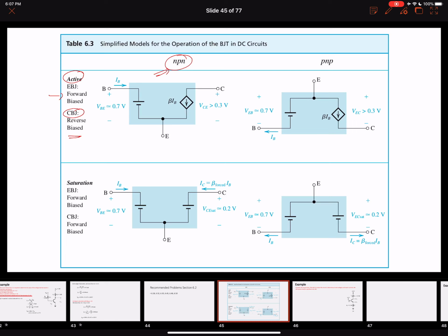So we end up putting this voltage value over here, where VBE equals 0.7 volts, which means that the emitter to base junction is forward biased. And we represented the emitter to base junction by a 0.7 volt source or a potential drop across it, if you remember the voltage drop model of a PN junction diode from the diodes chapter.